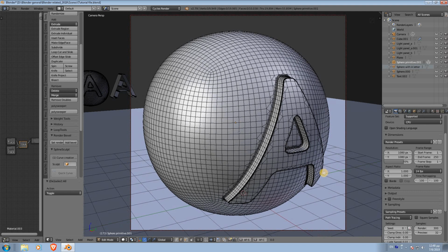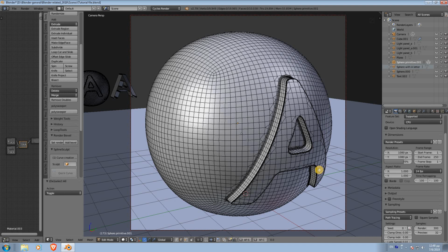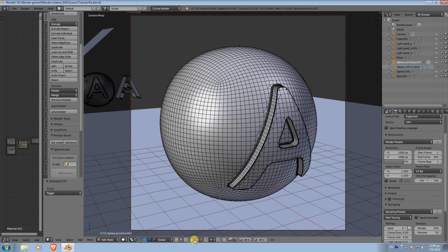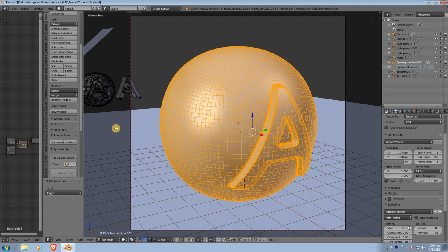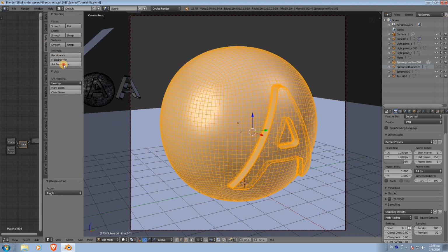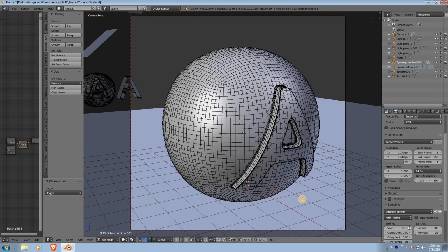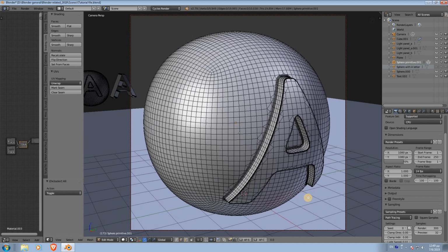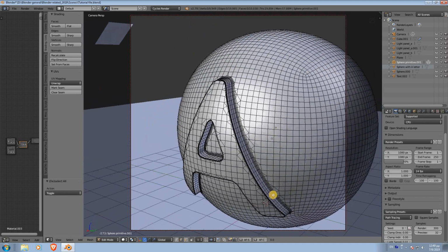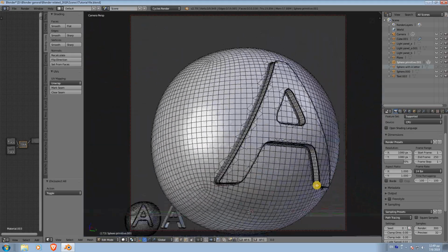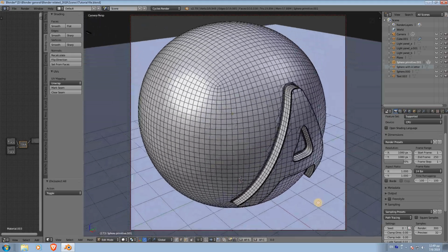And something that we have to do, not to forget, is going here, selecting everything, and then going to the normals, set from faces. It's the best method for being okay with the normals, and here we do have it ready now. Ready. As you see, it's quite clear.